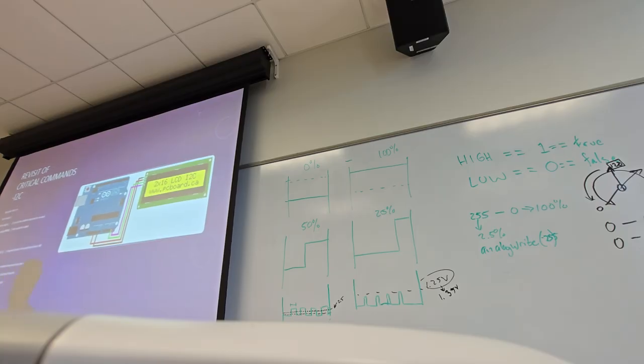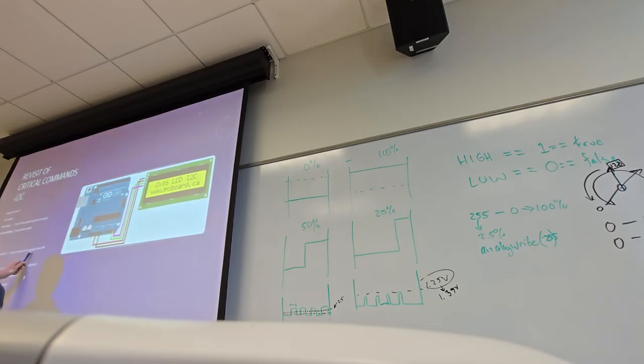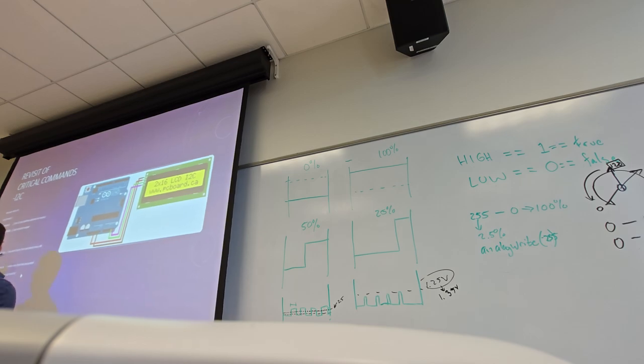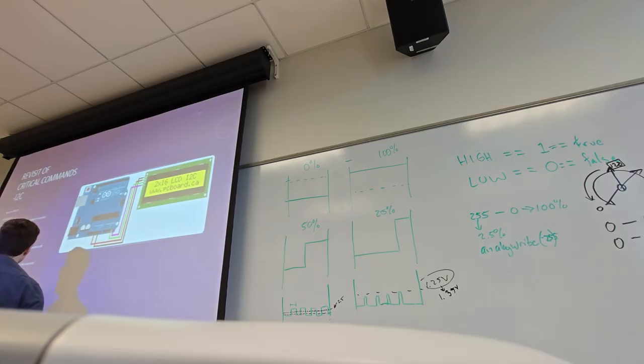So what will almost always happen is that we will request information from our device. Okay, so we're requesting 6 bytes of information from peripheral device number 8. There could be up to 255 other devices all on the bus. Each one could be a temperature sensor, a pressure sensor, or whatever.